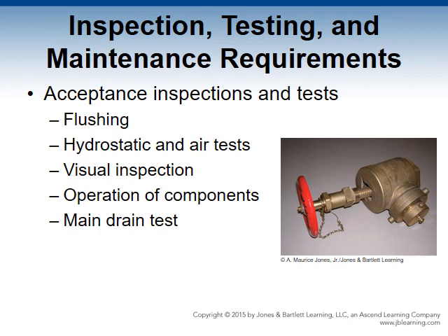Visual inspection basically confirms that the design and installation meet the minimum standards and are consistent with the approved plans. It determines if the system has any damage or leaks, if the components are the right size and correct in location, and if the components are the type specified. It is common to perform more than one visual inspection during system installation, concurrently with the hydrostatic test, operational test, and final inspections.